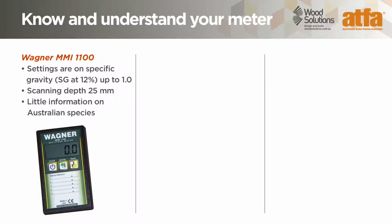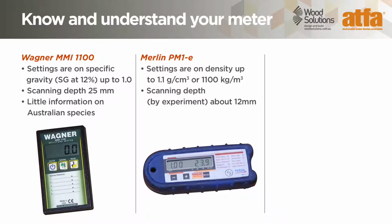It is important to know and understand your meter. Here are 3 examples. The Wagner MMI 1100. Settings are on specific gravity at 12% moisture content up to 1.0. Scanning depth 25 millimetres, and there is little information on Australian species. The Merlin PM1E. Settings are on density up to 1.1 grams per cubic centimetre or 1100 kilograms per cubic metre, and scanning depth, by experiment, about 12 millimetres.